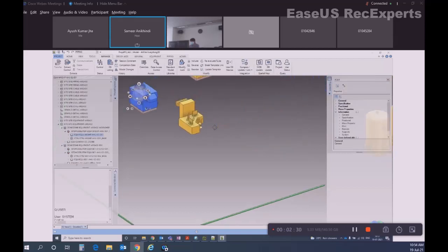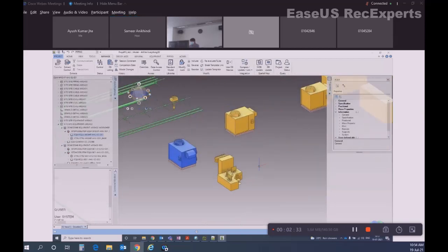Okay. So three types of right click menu: simple right click, control right click, and shift right click, applicable only when you are using an in-view command. Whenever it asks to snap a coordinate, snap a point, shift right click menu will work. Otherwise, it will not be working. Please try quickly.